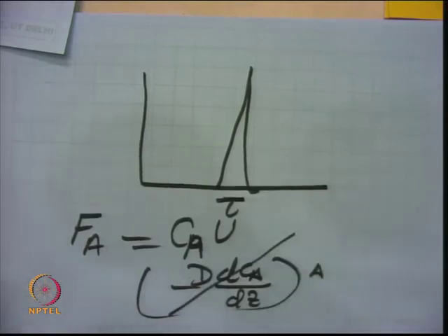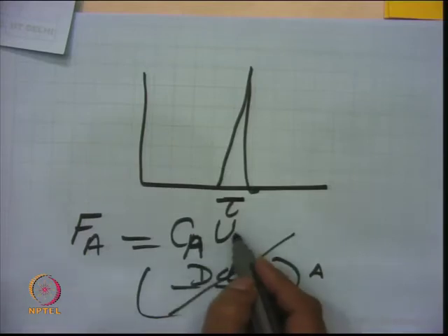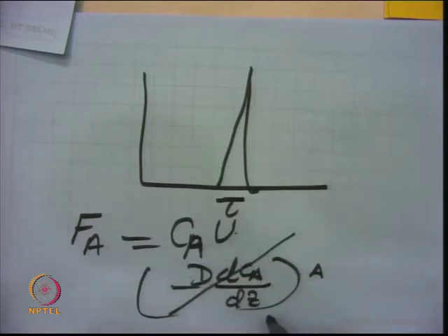You should maintain the condition such that the second term has no contribution, or zero contribution, right. So everything is because of the convective flow. This is the convective flow, this is your diffusive or dispersive flow, right, and when you have a large diameter reactor, there may be radial gradients also, right.